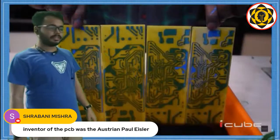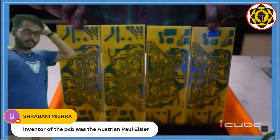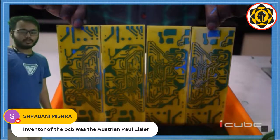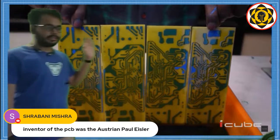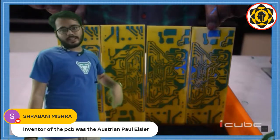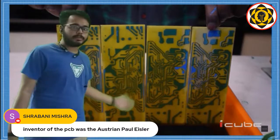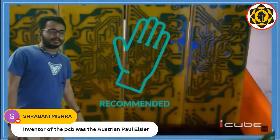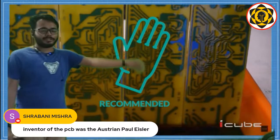So this is the PCB after washing with ferric chloride. After washing with an acidic substance like this, obviously wash it again and again with water, 2 or 3 times minimum, and wear a glove once again. See, I put it there as well. Glove is recommended.